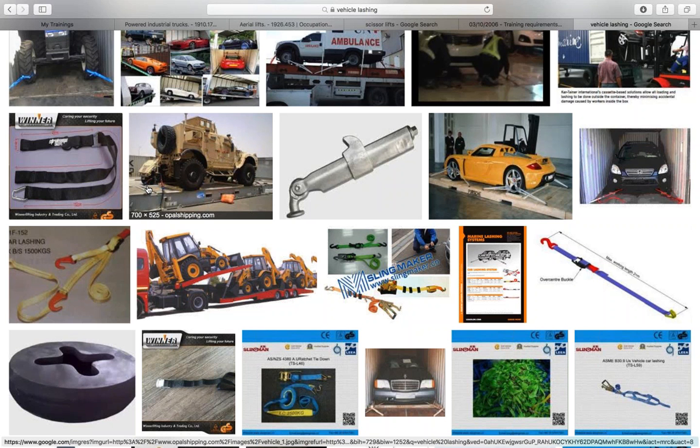Also, use retaining guards or safety devices on all equipment. If we can secure a load before moving it, in order to minimize how much it's going to move around, let's try to reduce that momentum. Also, report any type of defective equipment, material, or tools, and let's lock it out and tag it out of service if we need to. Disconnect that power and tag out that equipment. But not only tag it out, put why it's tagged out, and make sure you take that key out of it also.